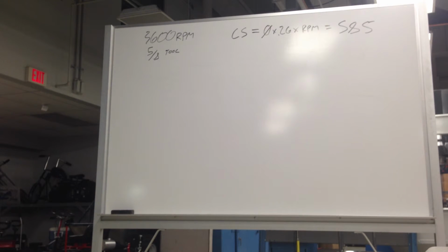You're gonna have an all-right surface finish. You could probably go better, but if I was doing a production job, 585 feet a minute. 585 surface feet per minute. So that tool is traveling 585 feet in a minute. In 1 minute, it can travel that much. And remember, you're talking about the rotational, right? So just think of that one chip moving along the surface.